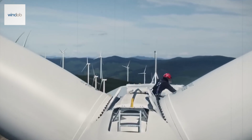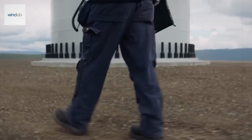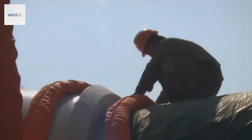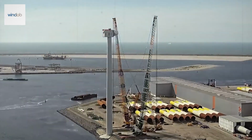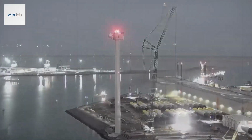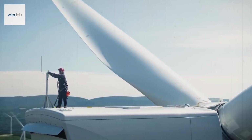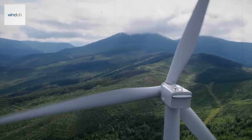To operate efficiently, electricity generators necessitate thousands of RPM, while a typical turbine blade rotates at approximately 10 to 20 RPM, revolutions per minute. The speed is multiplied by the transmission, which transfers the amplified rotation to the generator through a system of planetary gears. The generator functions similarly to a substantial alternator. Alternating current (AC) electricity is generated through the application of electromagnetic induction.